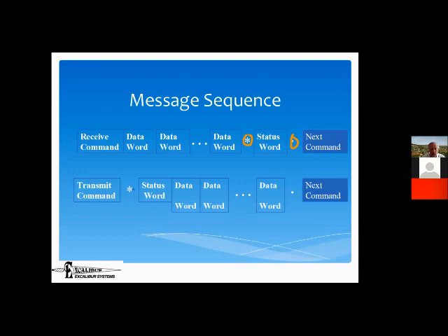And therefore, following the command word, we immediately are waiting for the response time. So now, again, we've got on the order of 10 microseconds to respond. The first word that the RT responds with is the status word. Following the status word and contiguous to the status word are however many data words were requested by the bus controller.